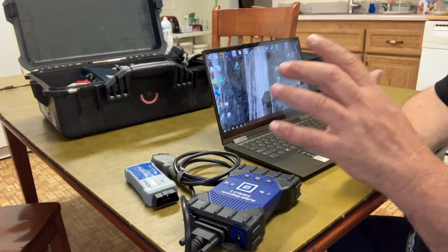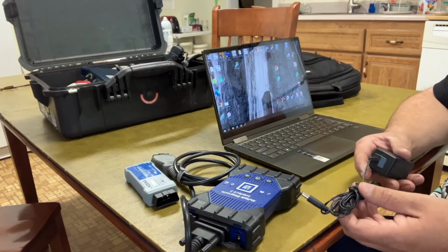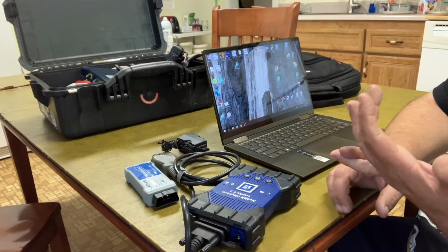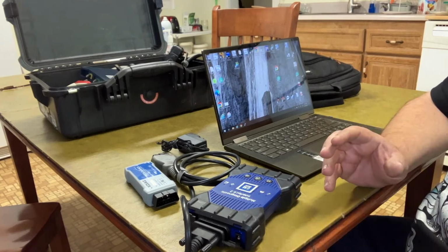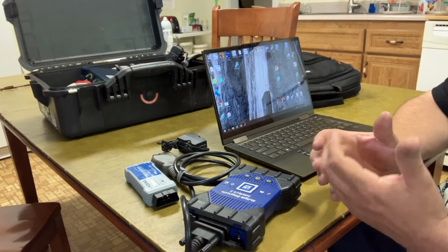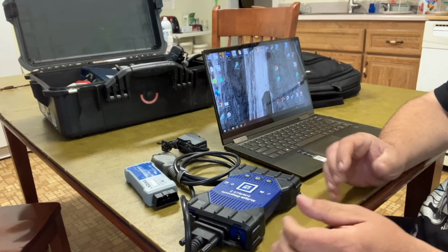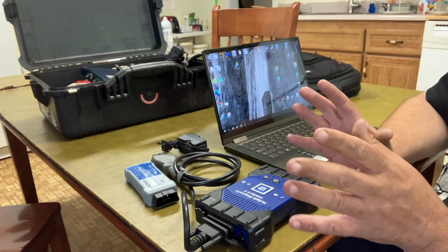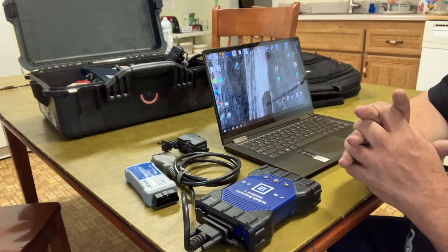Okay, so you want a backup power when you're programming because you don't want it to go down halfway through programming the module and end up breaking a module. You'll need like an extension cord. You can run it from a power inverter, or from whatever. I have a 60 amp battery maintainer that I hook up as well to make sure the battery stays charged while I'm programming, and it's an actual maintainer, and I'll take you out later and show you what maintainer I use. But if you're going to do BMWs or Eurotrash, I think the recommendation is 100 amps. GM, it's always worked fine with the 60 amp.